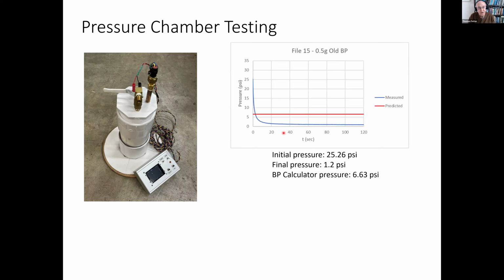And running the first test of 0.5 gram of black powder, you can see the blue trace here, we measured an initial pressure of 25.26 psi, and as the gases cooled, the pressure dropped to 1.2 psi at ambient temperature.